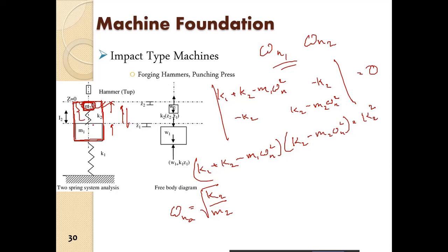So basically it means there is no relative displacement. Alright, we should not say absolute phase, we should say there is no relative motion between m2 and m1. So the spring K2 is not moving at all. It is not getting compressed or extended at all. So the entire mass m1 plus m2 is moving up and down as a single mass. So that is the limiting frequency.